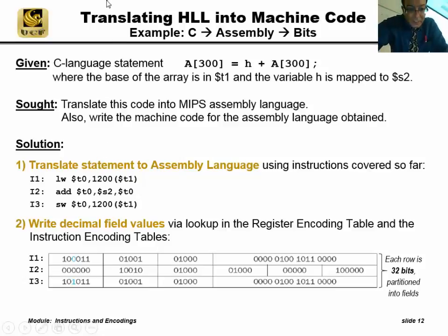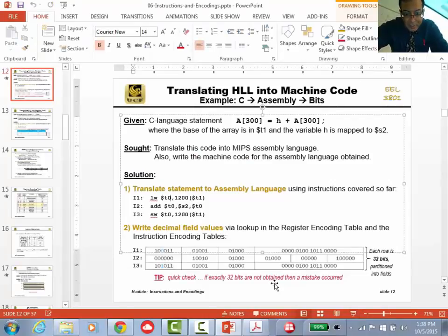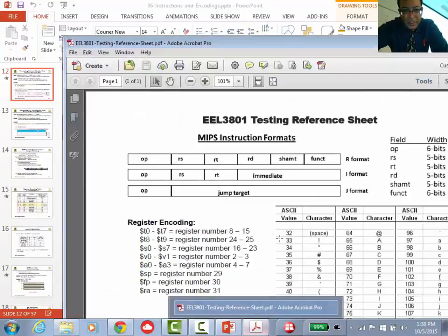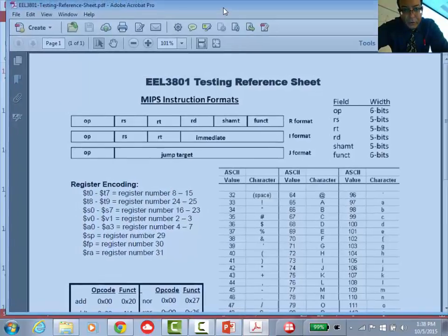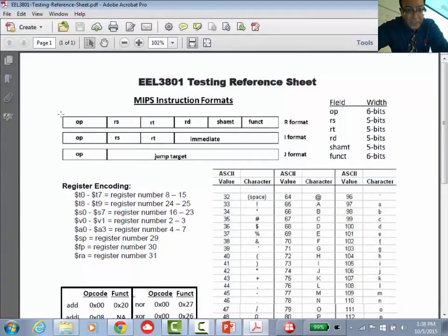This is one of the few exceptions. So normally when we look at this sheet, we've seen several already. Register format usually is not too tricky or too complicated, and there are only a couple of exceptions. Load word is one of them, but you can see that if we have register format, RS, RT, RD, when we write it as assembly, RD is the first operand, closest to the opcode.